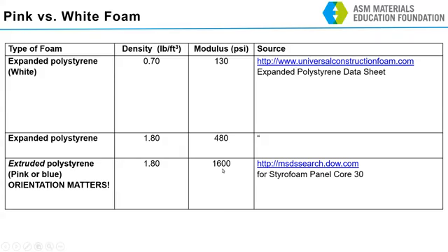One thing that we learned the hard way was if you're cutting samples out of the extruded polystyrene, you'll see almost like a wood grain on the surface of it. It matters whether you cut the samples parallel to the long part of the rectangular sheet of insulation or perpendicular. We gave a work study instructions to get as many beams out of a sheet of polystyrene as we could, and we were seeing big strength or stiffness differences in the two directions. And you'll learn, well, when we learned about polymers and chain alignment the other day when we pulled on our garbage bags, that's what we're seeing going on here.